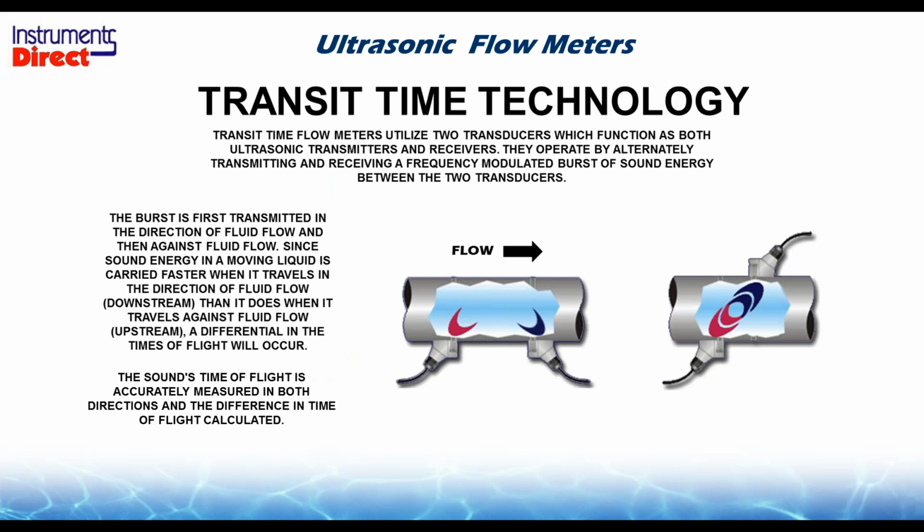The other side of the coin is the clean liquid ultrasonic flow meters. And the clean liquid ultrasonic flow meters are called an ultrasonic transit time. Now the transit time is a more accurate beast than the Doppler. And the transit time variations are, it works on applications with no suspended solids. So sewage is a strange beast. Sewage is traditionally water. Residential sewage is water. Most commercial sewage is just water. A couple little chunks of stuff, so to speak. So transit time technology will work on sewage.